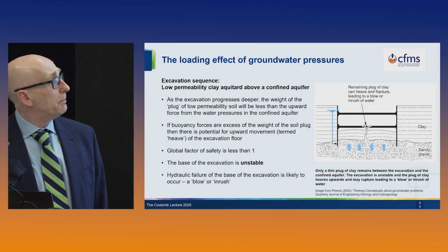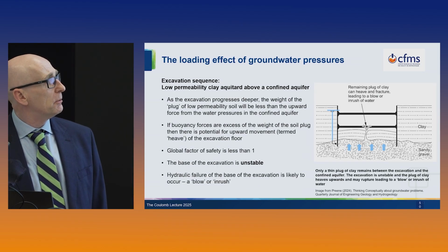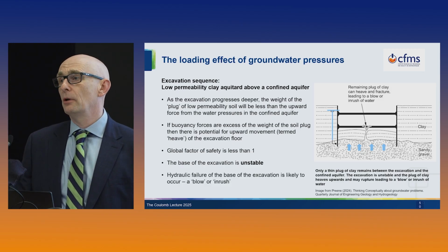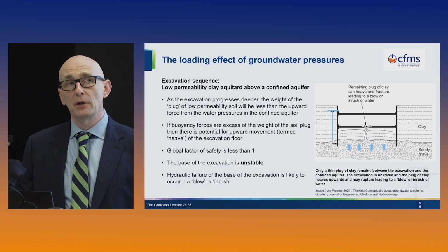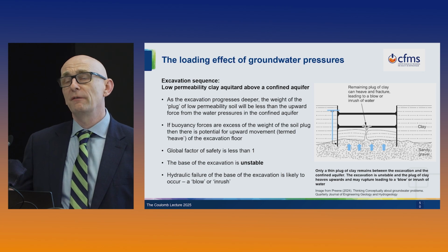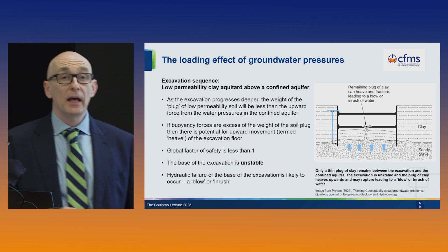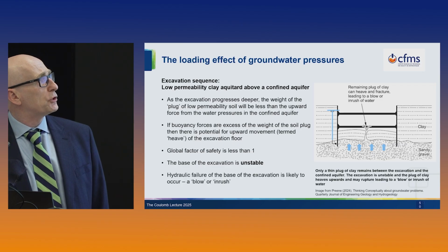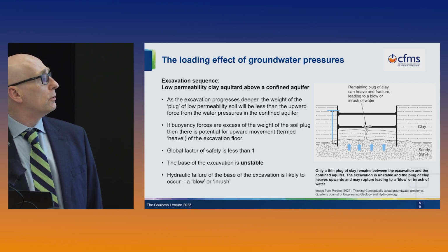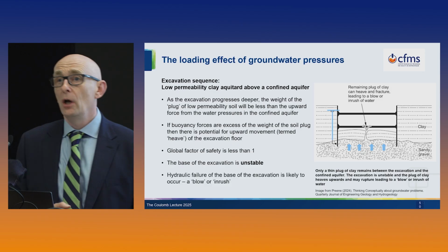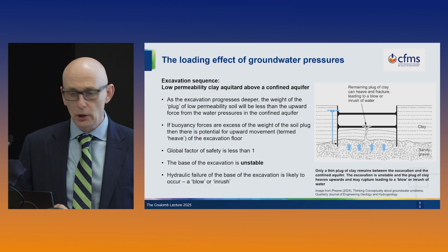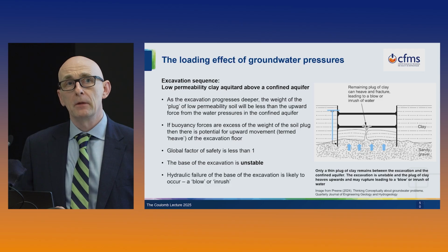But as we go down deeper, this plug is going to become thinner and thinner, and eventually a situation will occur where the weight of the clay plug is insufficient to resist the upward groundwater pressures. We would say that the global factor of safety is less than 1, and then there'll be some movement and heave. This clay will probably rupture, and then we'll get an uncontrolled inflow of water. And in English we would call that a blow or an inrush. There are often various colourful words for it.